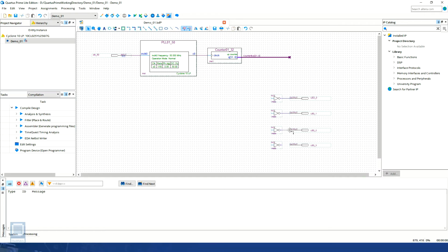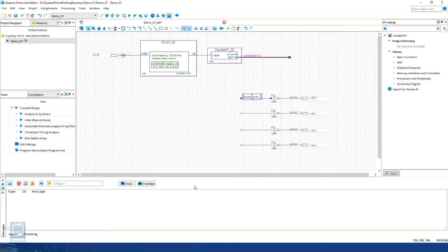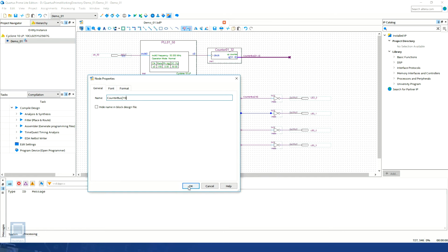But in order to access the input of the NOT gate, we'll need to extend it using an orthogonal node tool. We will just draw a node and leave it hanging a little bit away from the NOT gate, like this. Now we can assign each node a bus pin's name to link them together. That way they will carry the same logic. It's like they have some kind of invisible wire connecting them, so let's just do that.